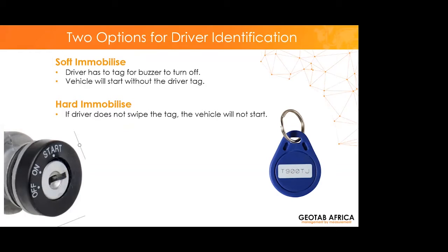Take note, with the soft immobilize, the vehicle can start, but the buzzer will keep on buzzing. Option 2, hard immobilization. When a driver gets into the vehicle to start the trip, if the driver does not swipe the NFC tag, the vehicle will not start.